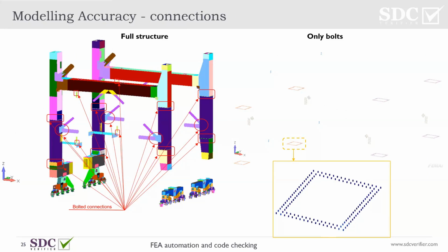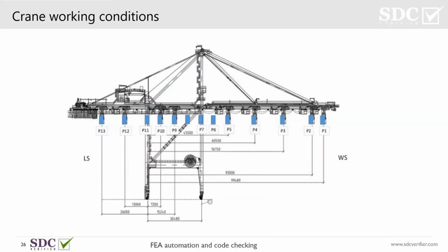The next thing I was talking about is the loads and the real crane working conditions. Just a short background: if we have a trolley, it's picking up the load and putting it down somewhere, moving in that direction, then moving back. So basically it creates the vertical load. Our crane is able to travel, so it also creates some inertial forces from the crane, from the lifted load, and so on. These complex working conditions end up as separate load influences.